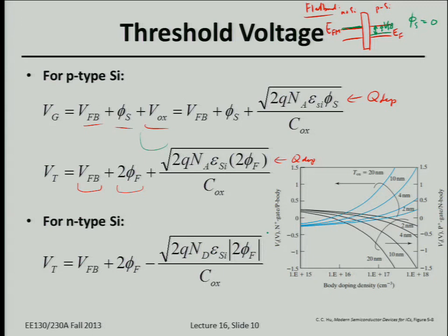As you increase the dopant concentration, the threshold voltage increases. Qualitatively, if you make the substrate more p-type, it becomes harder to invert the surface. Does that make sense? You have to apply more voltage to change the surface from p-type to equally n-type. The more heavily doped your silicon is, the higher the threshold voltage will be.